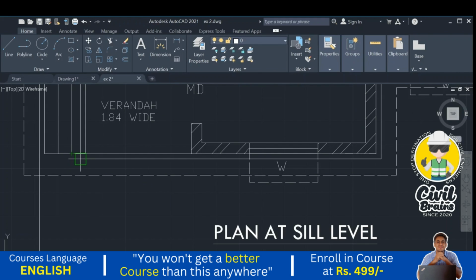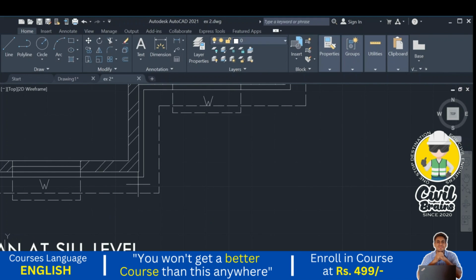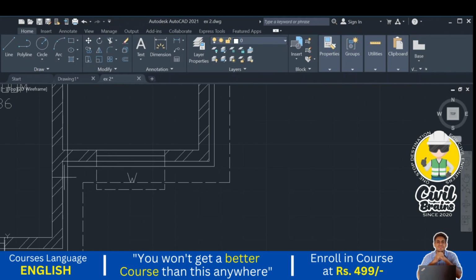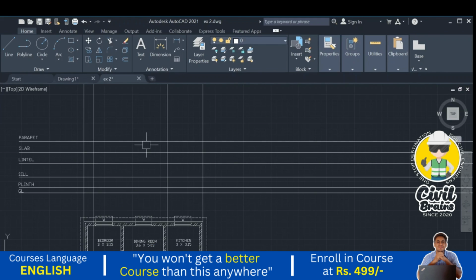Next, these corners we need to project. Next, plinth corner, not the wall corners, we are showing the plinth line here, this corner, and this corner, the same thing, and this corner. Okay, so we have projected here, so extra lines we just delete.